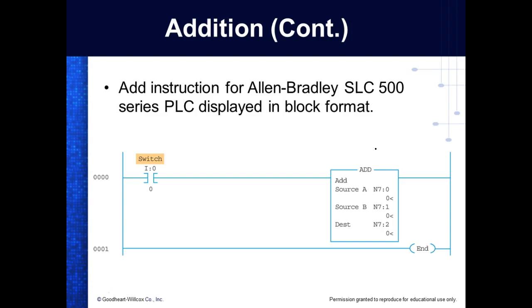When you're writing the program, it has no idea what's out there in N7:0 while you're writing, right? Understand? Because we're not online with the PLC on the right program. So by default, it's going to put that 0 in there. As soon as you go online, download and go online, it should put the numbers that are coming from that file. That's a good question too.